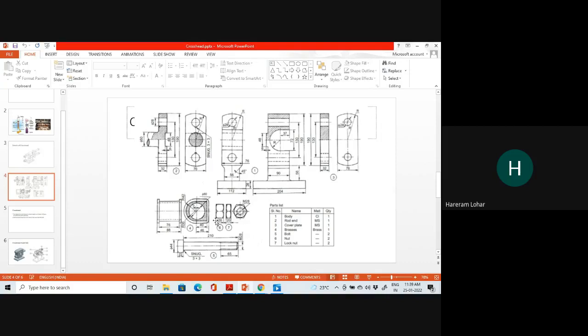When you drew the nut in machine drawing one, you know that the height of the nut will be the same as the diameter of the hole, 28. And again some chamfering will be there, because the outer edge of the nut should not be sharp. Again we know that when sharp edges are there, stress concentration at the sharp edge will occur due to the sudden change in geometry.